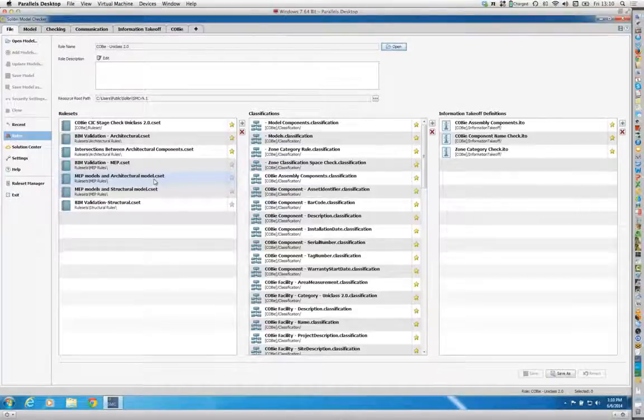One word of note, the Uniclass 2 version here needs to be updated with the classifications. The CPIC website has a different version of it, as it's been improved basically since this was created. It was created for the Cobie trials, and the template was also created for the Cobie trials. We have a customer in the UK who is currently being asked to generate a Cobie Uniclass 2 deliverable by the client rather than a 1.4 version, and we're in discussion with Nick Nisbet to generate another template file so that it can actually be released.